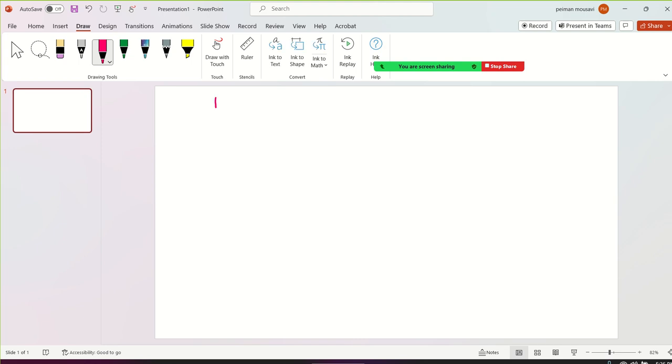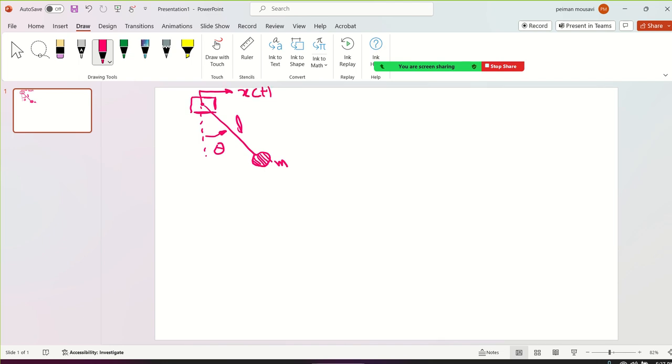So remember that we derived together the equation of motion for the most fabulous example, the particle pendulum, in the last class. For refreshing your mind, you saw that if the base, the hip of your body, has a displacement x that is changing with time, we derived the equation of motion, which was nonlinear: theta double dot plus g over L sine of theta. That was a nonlinear differential equation.